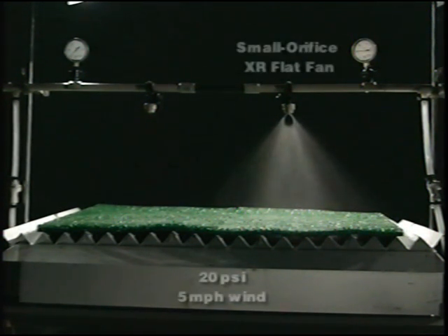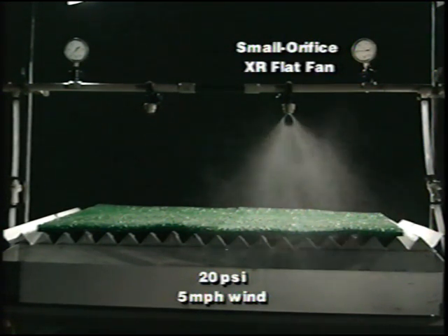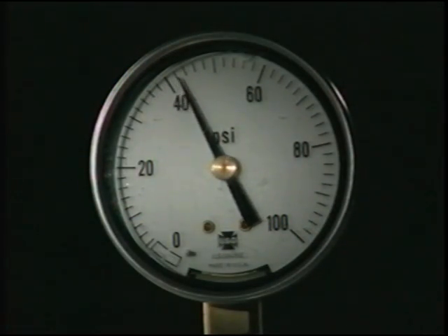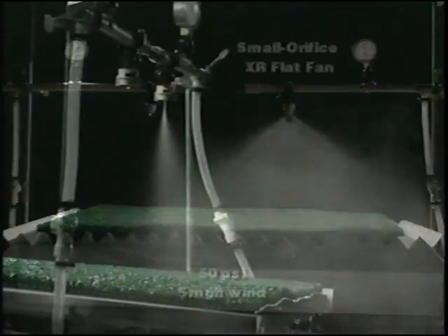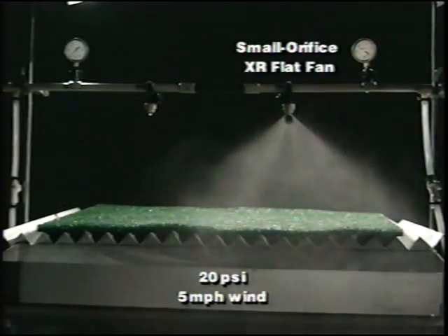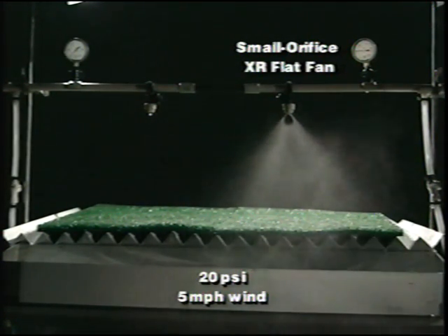But using this small orifice extended range flat fan nozzle in a simulated 5-mile-per-hour wind, we can see, by increasing spray pressure to 40 psi and above, the creation of an abundance of micro-sized droplets, an obvious increase in drift that actually reduces coverage. Now, by lowering spray pressure back to the 20 psi range, we can create larger droplets, in turn reducing the potential for drift.